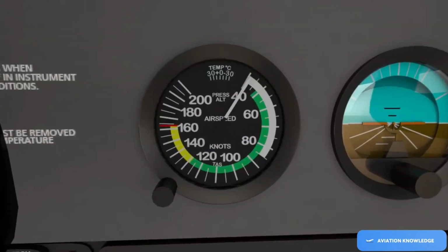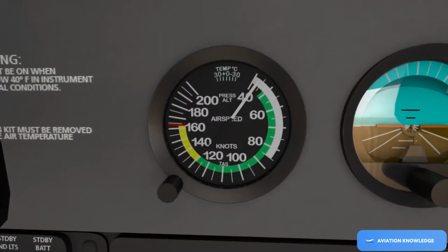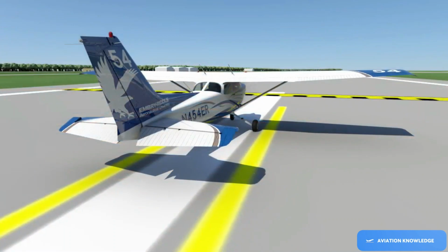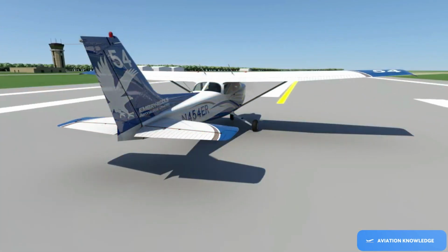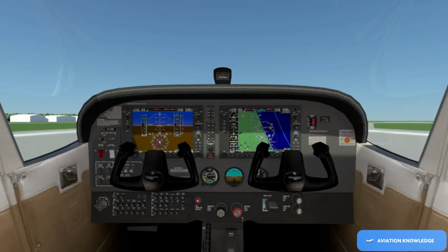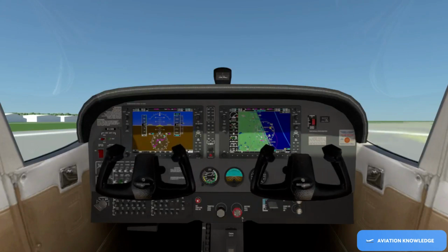As the airspeed is increasing, the controls will become more effective. This is due to the increase of air flowing over the control surfaces. Most notably, the airflow under the elevator will actually bring the surface into its neutral position. You will feel this happening as the yoke slides aftward, towards you.